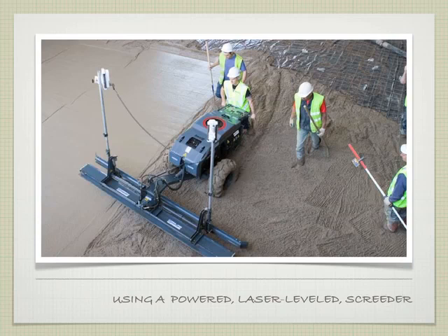So if you're doing a really large scale pour, you still need to get this roughly smooth, so that it's in its correct placement. This would be almost impossible to do by hand, because how would you know where it was too high, where it was too low, that kind of thing? So you use something like this. It's a machine. It will do the screeding for you. Obviously, in the back, we see the rebar, not covered completely by concrete, and they're working their way out from here. Make sense?